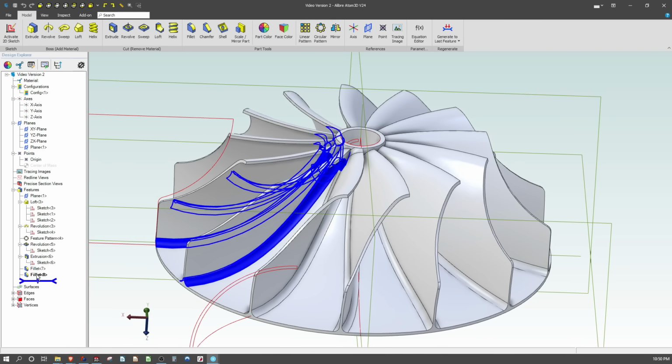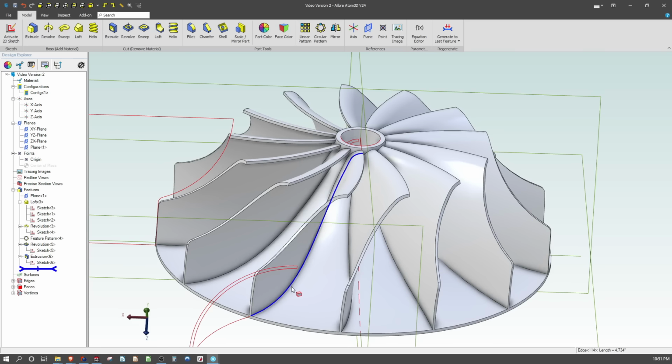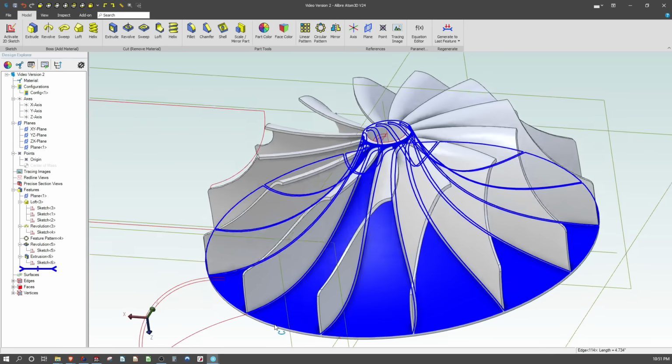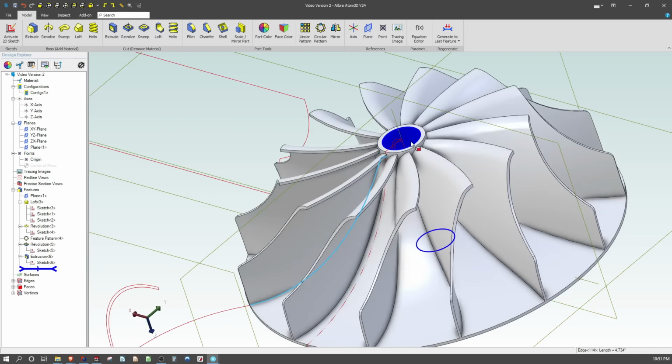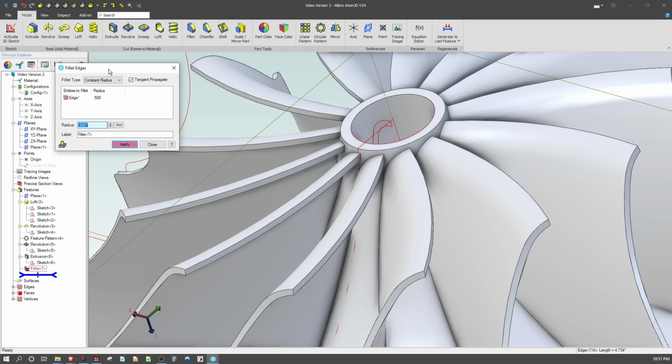So we have a compressor in Alibre. Let's actually get rid of these fillets here. And I highlight an edge over here. Alibre has a nice little feature where I can come in and choose fillet, but I can check and make this variable radius. And then I'm given a start and an end radius. Right? So my start radius, if I make 0.02, and my end radius, I should switch these actually, 0.02 and maybe 0.05.